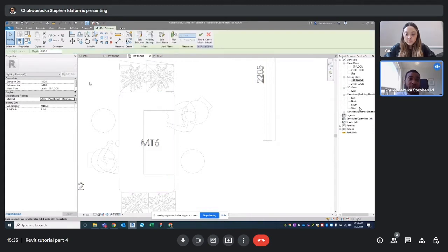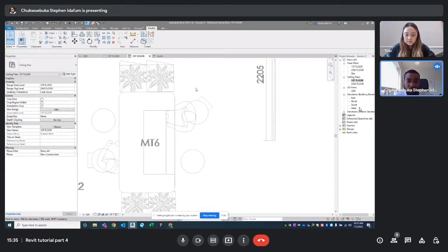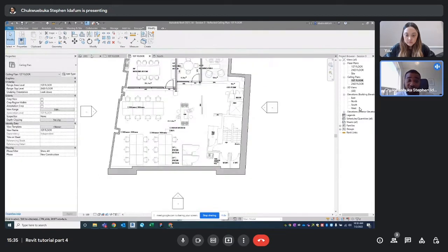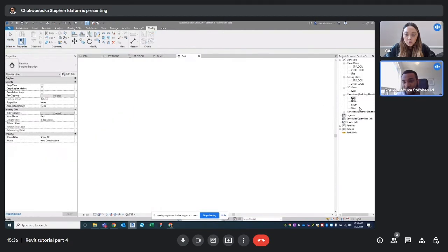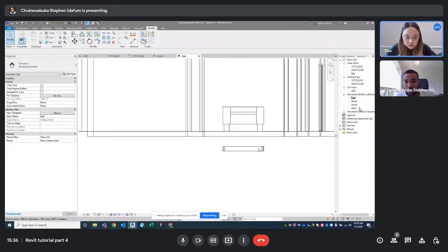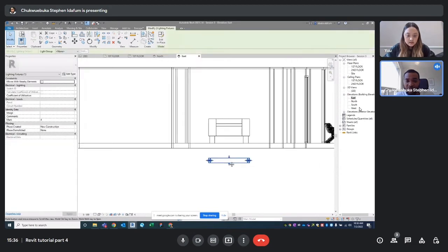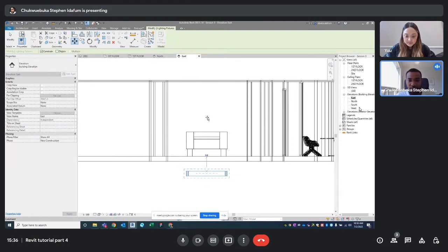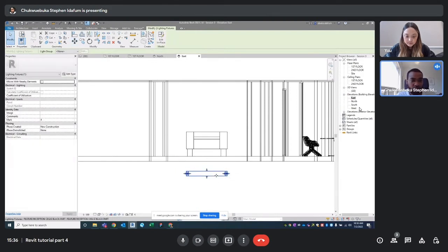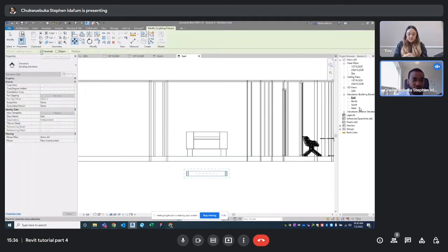So now we've created our extrusion. Press finish model. Now we actually have to see how it looks, because okay, let's see. Let's go to elevation. So the one we just drew, okay, is there? Ah, okay. We messed up the ceiling, but we can just move this by typing MV. So Move. We've got this. Okay, now it has a constraint. In order to move it, when you press MV, you have to check off the constraint here.